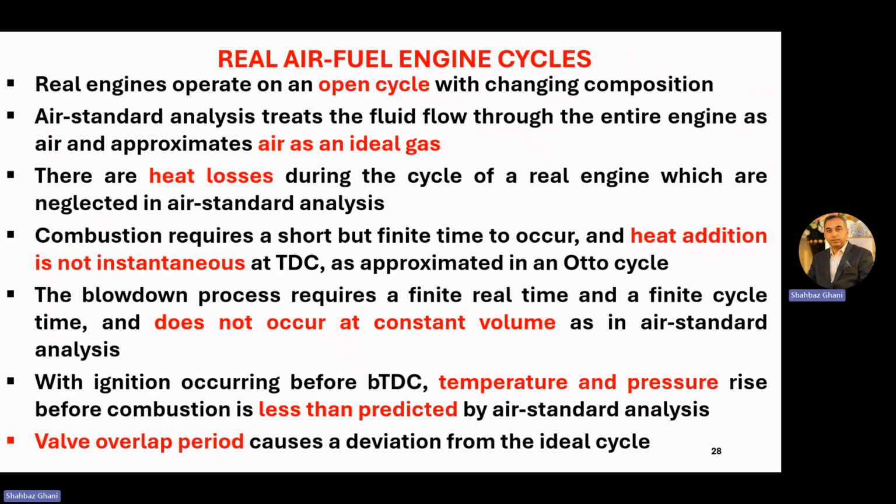Now, real air fuel engine cycle. A real engine operates on an open cycle with changing composition. So there is a difference between the standard Otto cycle and the real engine cycle. Air standard analysis treats the fluid flowing through the entire engine as air and approximates air as an ideal gas. But at every instant, the pressure is changing, the temperature is changing, the composition is changing.